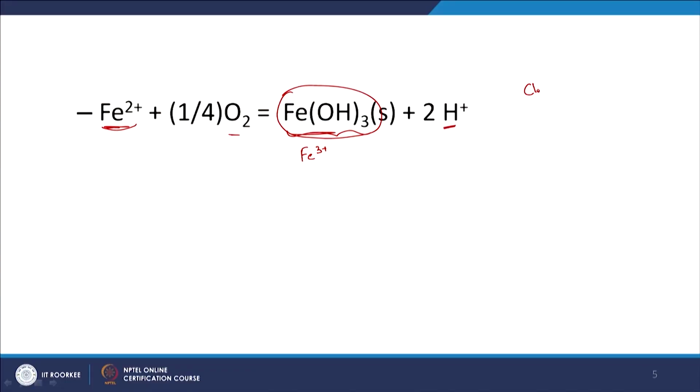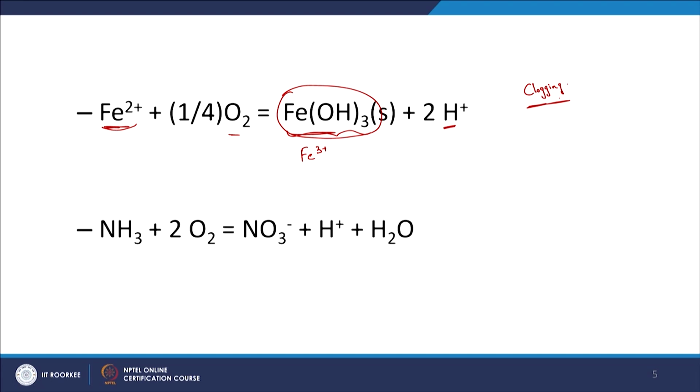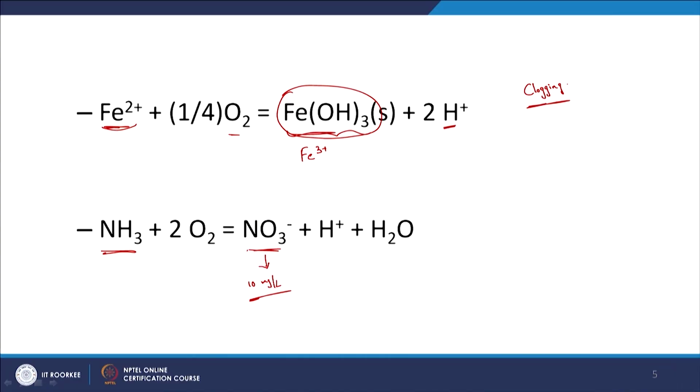So what will that lead to? That can lead to clogging, right. Your relevant pores can be clogged now. So that is something to keep in mind. And also this iron has an oxygen demand, that is what you see out here, right. So these are some aspects to keep in mind. Or obviously NH3 too can be oxidized to NO3-, and keep in mind that NO3- is a toxic compound, and I think we have around 10 milligram per liter drinking water quality standard that is required for NO3-.